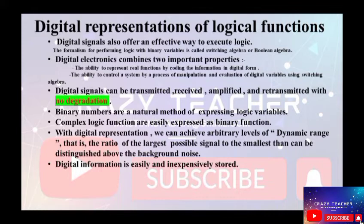But in case of digital, if I know that a 1 will be transmitted as plus 12 volt and a 0 will be transmitted as minus 12 volt, we can safely say anything above 0 is possibly 1, and anything below 0 volt is possibly a bit 0. So this is the amount of noise margin or noise immunity that we have in the digital system. It is going to be much more compared to the analog system.